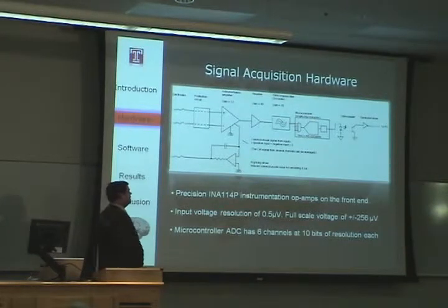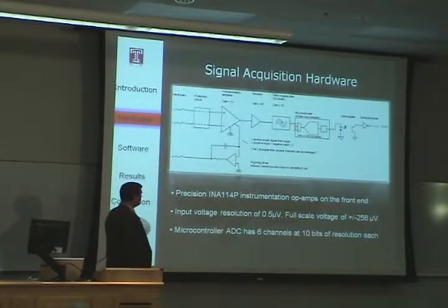Now this is a block diagram of the Open EEG system. This shows 2 channels coming in at the electrodes here. The signal first goes into an initial amplification stage, where it is then passed to a second amplification stage before going through a low-pass filter, which removes any 60 Hz AC noise that can come through the electrodes. From the amplification stages, it's passed on to the microcontroller where it is acquired and sent into the serial line, where it's finally sent to the user's computer.